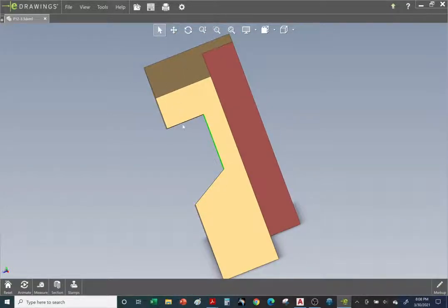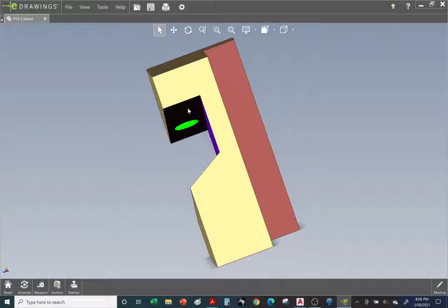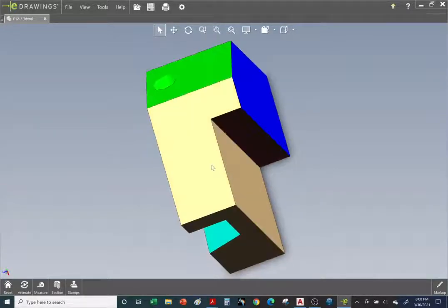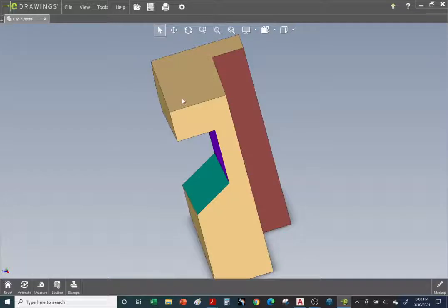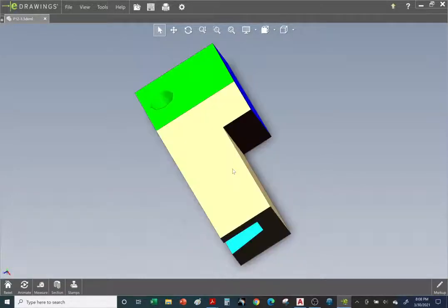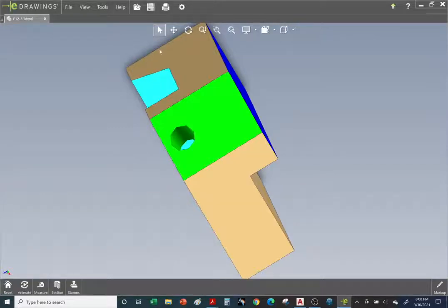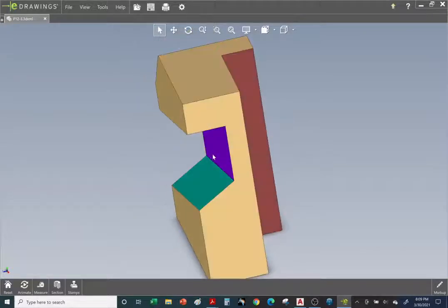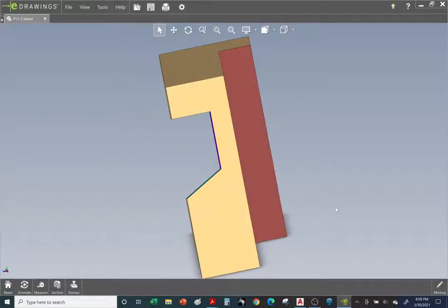And we do have the hole, right, going through, which we cannot see. We can't see the hole from this perspective, so we need to draw it, exiting at the bottom. Okay, and we need to draw these lines, I believe. Then we have hidden lines going across that we cannot see. So we need to draw this edge as a hidden line and this edge as a hidden line from this perspective. Right? So let's go back.